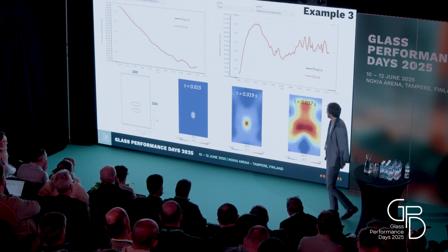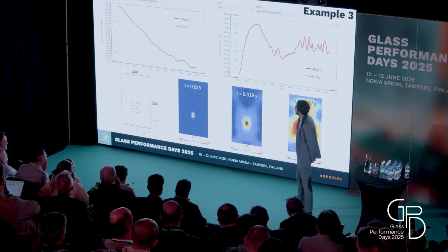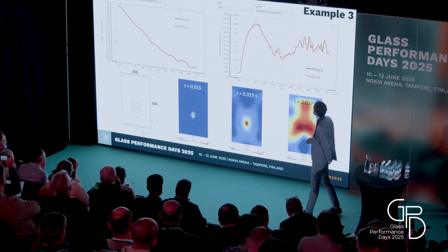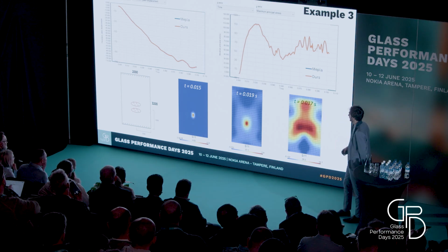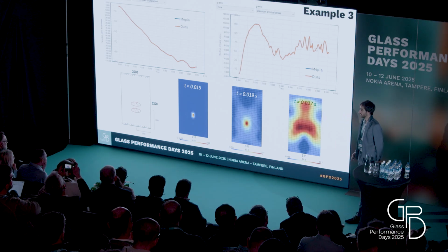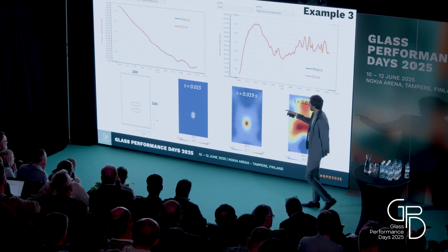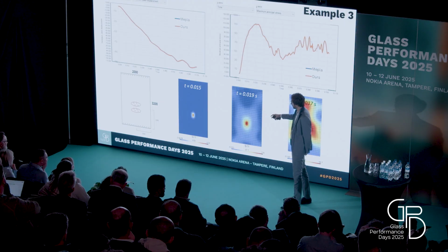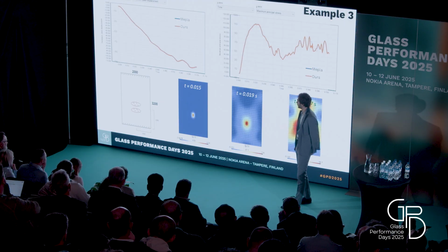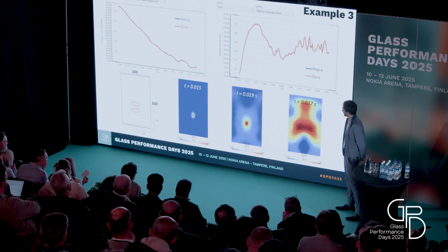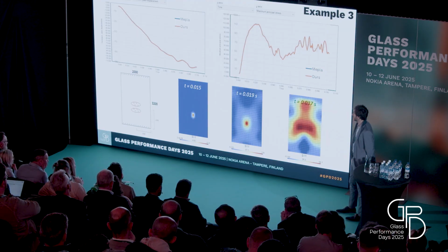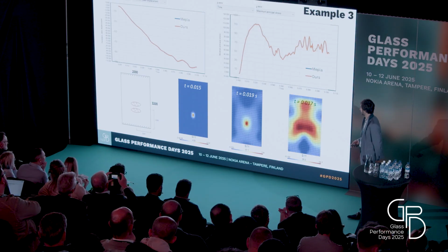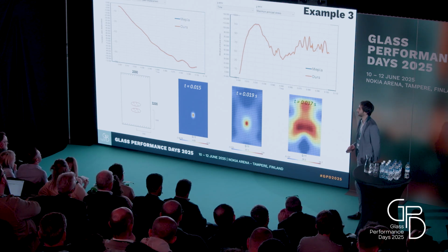And here's the result with respect to MEPLA. It's time versus maximum displacement, which is very similar, and also time versus maximum principal stress. You see here 3 typical times. At the first one, time 0015, you see the 2 ellipses for the stress when the pendulum is impacting on the glass. The second time is at the peak of the stress. And the third time is when the pendulum detaches from the glass and the laminate freely oscillates.